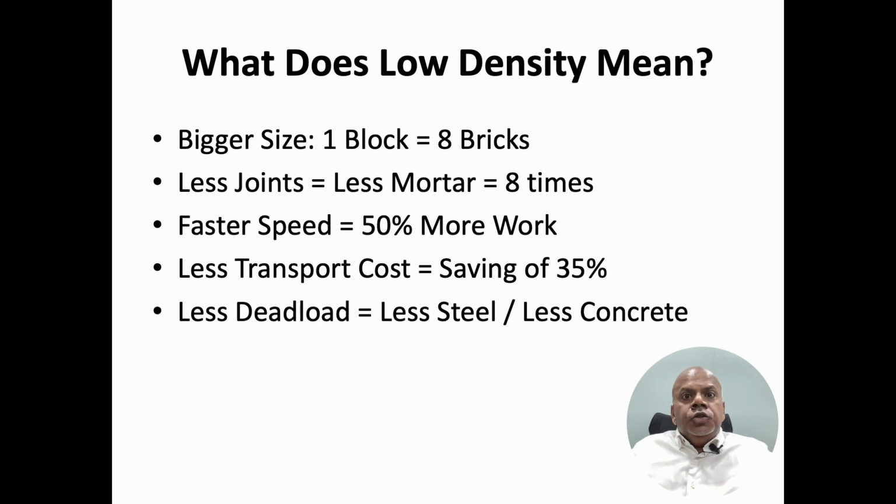And you are making your building, your high-rise building, and you are reducing so much weight from the building. This is a dead weight. You don't need it. This is just masonry walls. Why you need it to be heavyweight? So you can make your columns, your beams, your foundations with smaller sections. You can use less concrete. You can use less steel. Why? Because the load of the building has reduced substantially.